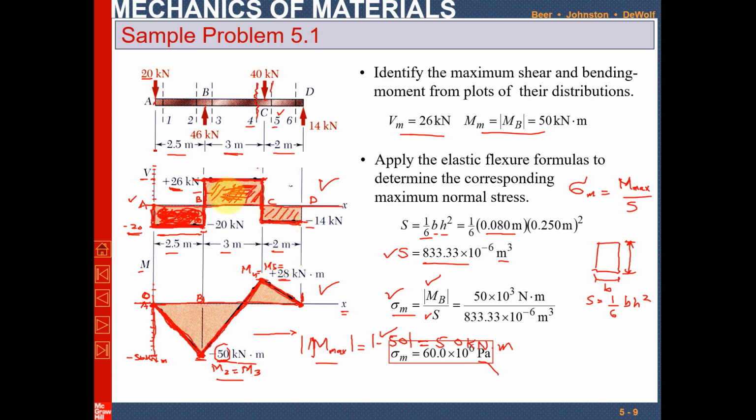So again, the area under the shear force diagram for any section will give you the bending moment. So if you do not know the bending moment at the start, you can also find it out for a quick finding of the value of the bending moment. So you can also check that the bending moment in this section AB will be this, the bending moment between B and C will be this, and the bending moment between C and D will be this, and this can be calculated by using the area under the shear force diagram.